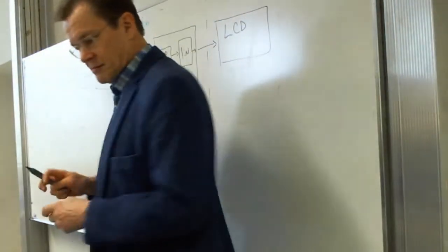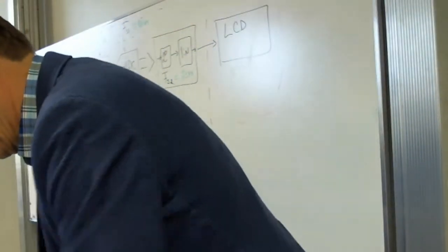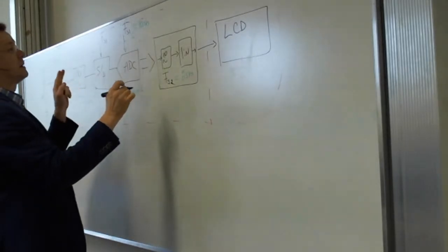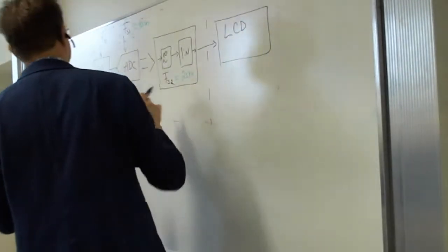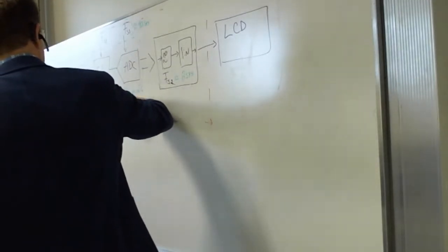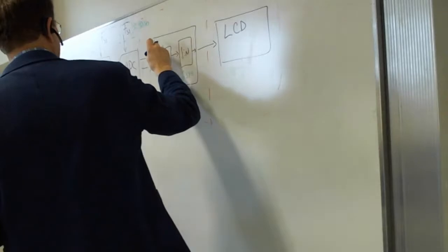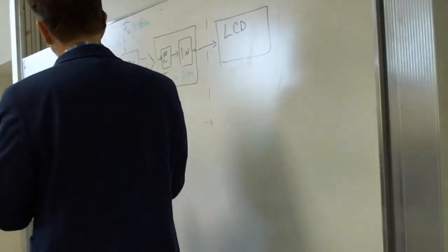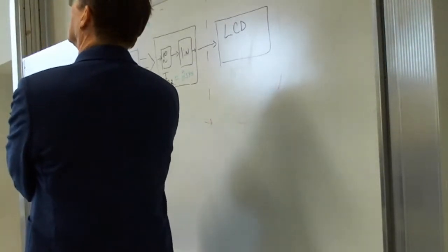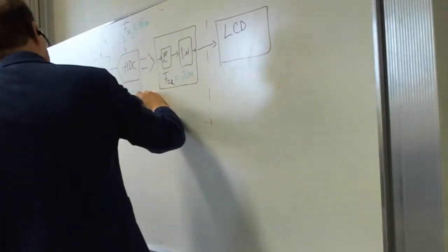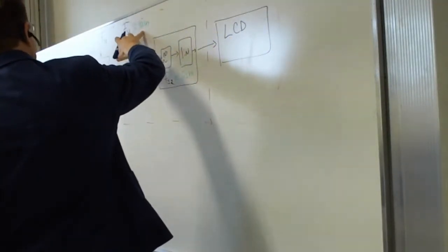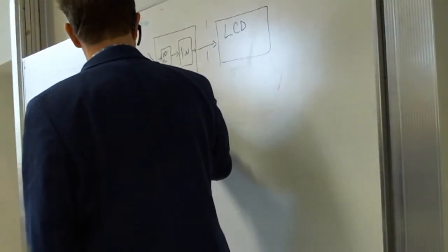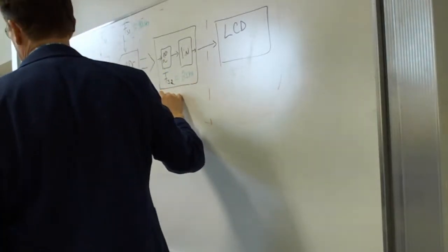So in principle, what your program should do there is to have a free running A to D. Actually, this is okay. Let me think it over. Yeah, actually, it works. So basically, this is free running. We have roughly 100 samples per second, but here you should have about 2 samples per second. This timing you can do with the sleep timer.